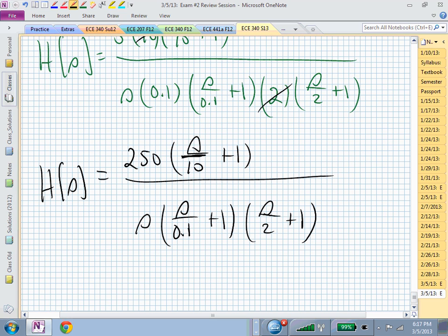By the time we've reached this point, we're now sloping at 60 dB per decade, because we have 3 poles in effect in our magnitude before we even get to our 0, and this will back off on the slope by 20. So we'll be going eventually down at minus 40 dB per decade, which is what we thought. Is that clear?